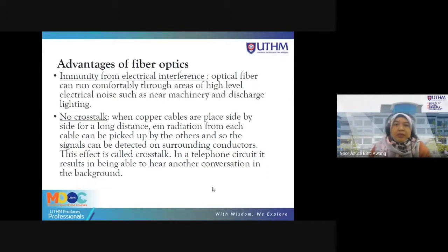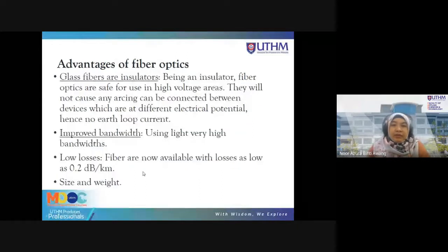Okay, another one is that glass fibers are insulators. Being insulators, fiber optics are safe for use in high voltage areas. They will not cause any arcing, and can be connected between devices which are at different electrical potential, so there is no earth loop current.